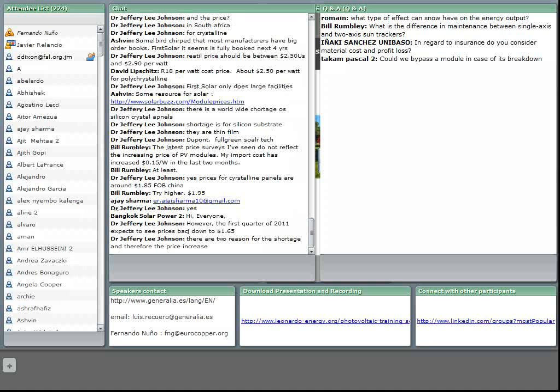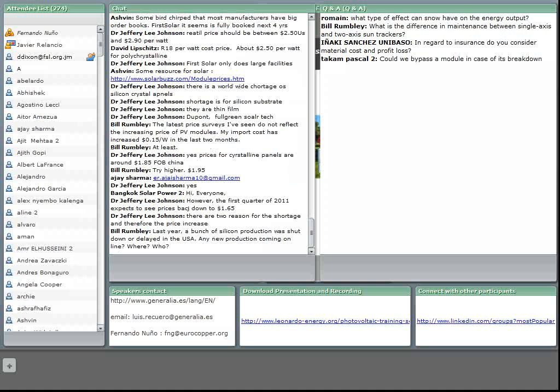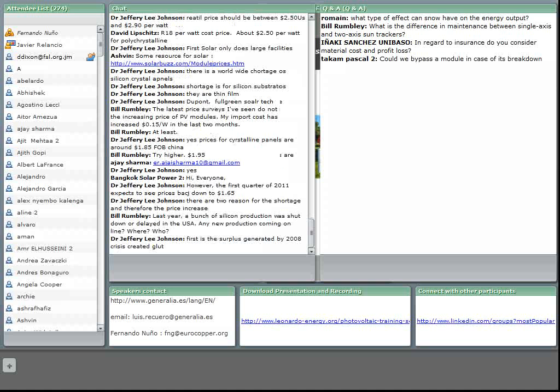So if we have less voltage in a module series than in others, we can even produce damage to the rest of the modules within that area of the installation, because that series will have less voltage than the rest of the series connected in parallel. So we have to be careful with this kind of solution, because the best solution could be doing a bypass on the whole series in order to have the same voltage in all the area.